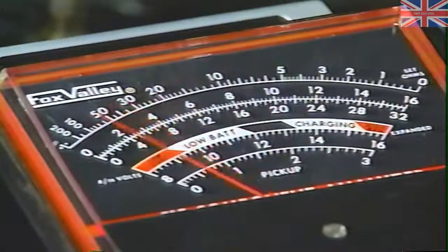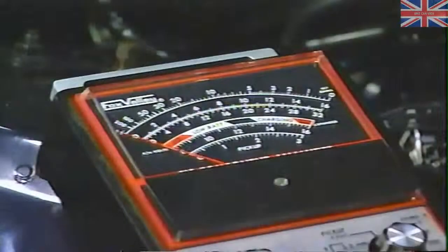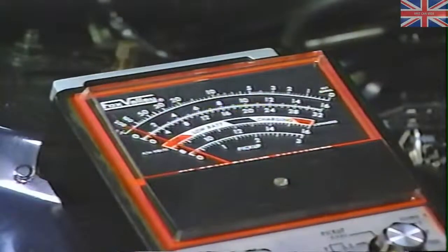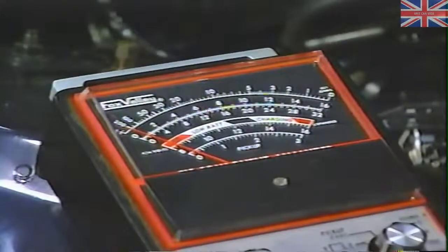The analog voltmeter, the dashboard indicator light, or the scan tool will all give the same results, and all will read out the hard fault codes held in memory or detected during the functional test. We are receiving a code 11, which is an indication of a pass. No fault codes detected at this time. After a few seconds, we will receive a code 10 on the scan tool, or an individual pulse on the analog voltmeter. This is called a separator code.